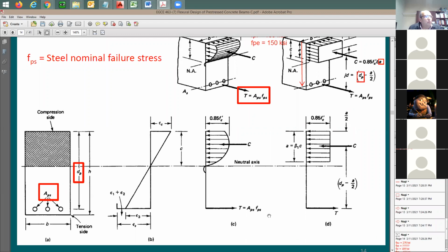Now, someone's going to say, would it be okay if I add some pre-stressed strands at the same time with some AS, some conventional steel? For example, here are the pre-stressed strands, and right below them, I can add maybe 3 rebars. What's your reason for these rebars? You're going to add some rebars top and bottom, and then you say, I'd like to control the cracking of the beam, and I want to be sure that if someone puts this beam upside down, it's not going to fail.